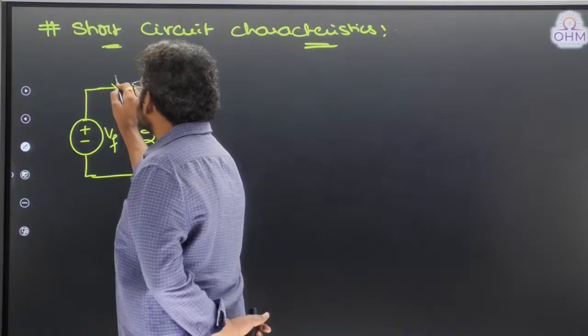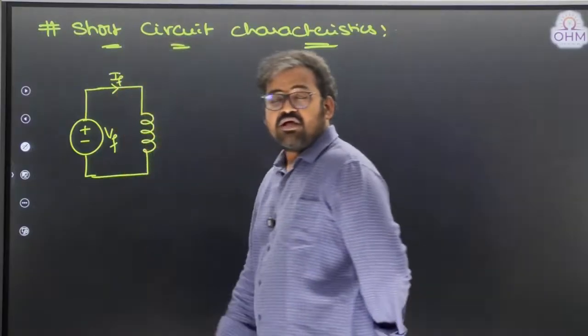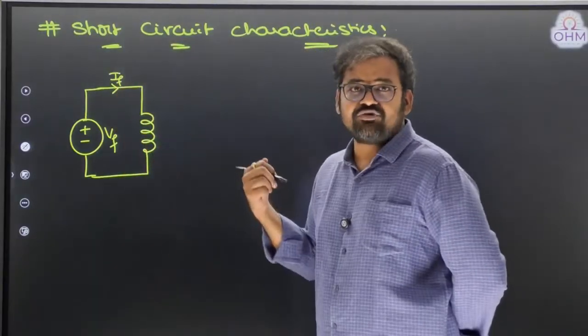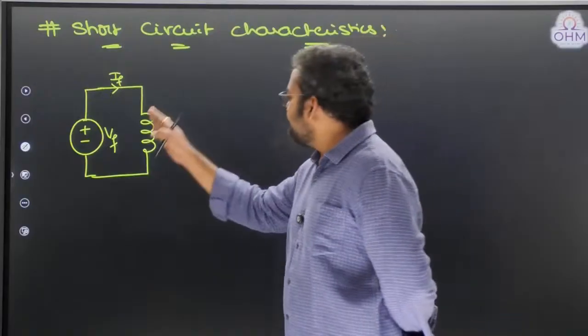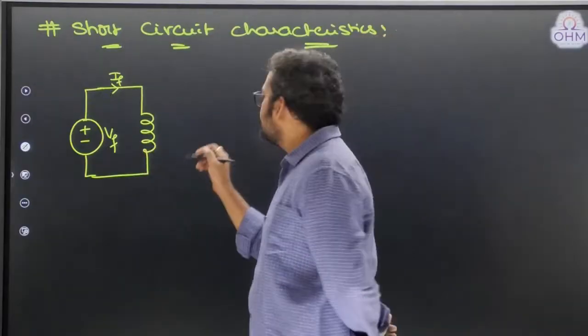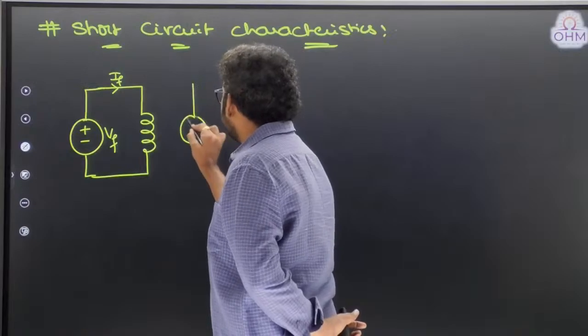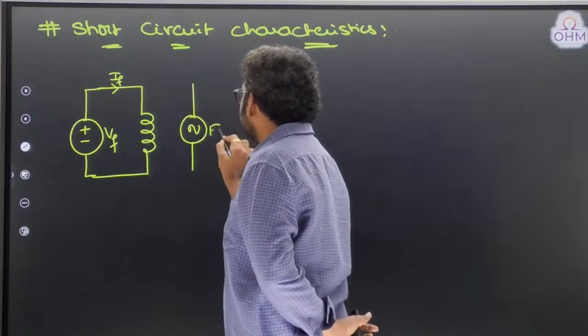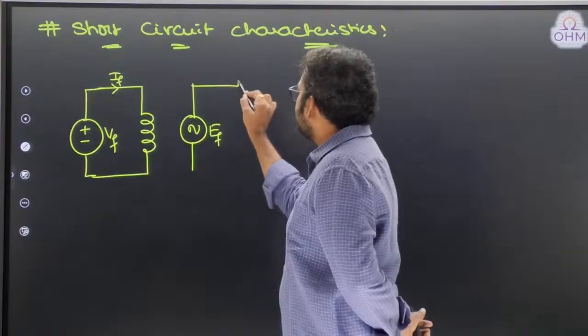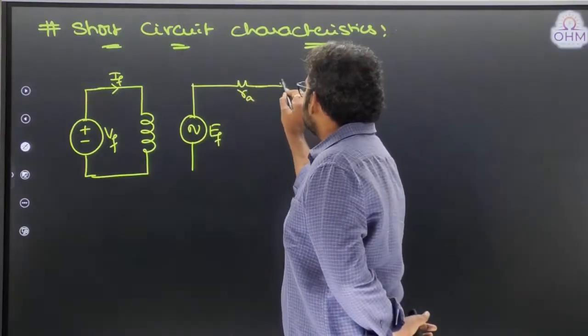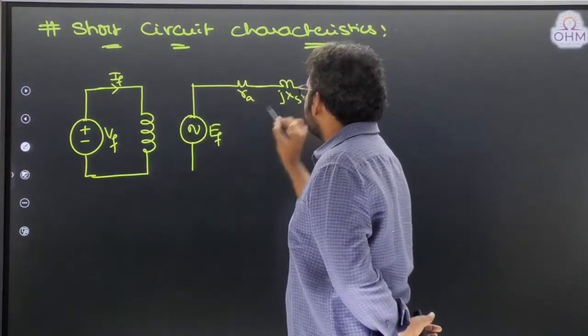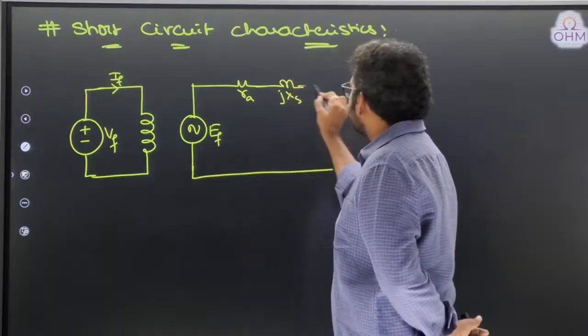This is a field voltage and the current is a field current. That field current will create a flux. We call it a field flux. That field flux will cross the air gap and link the armature winding. An EMF will be induced. We call it a field induced EMF. And then we have armature resistance, synchronous reactance, and finally the terminals are available here.